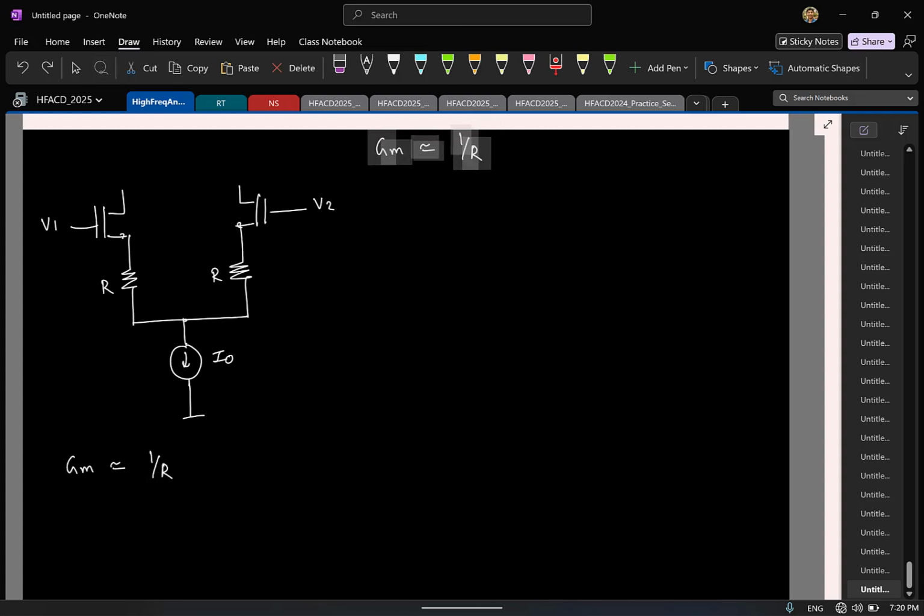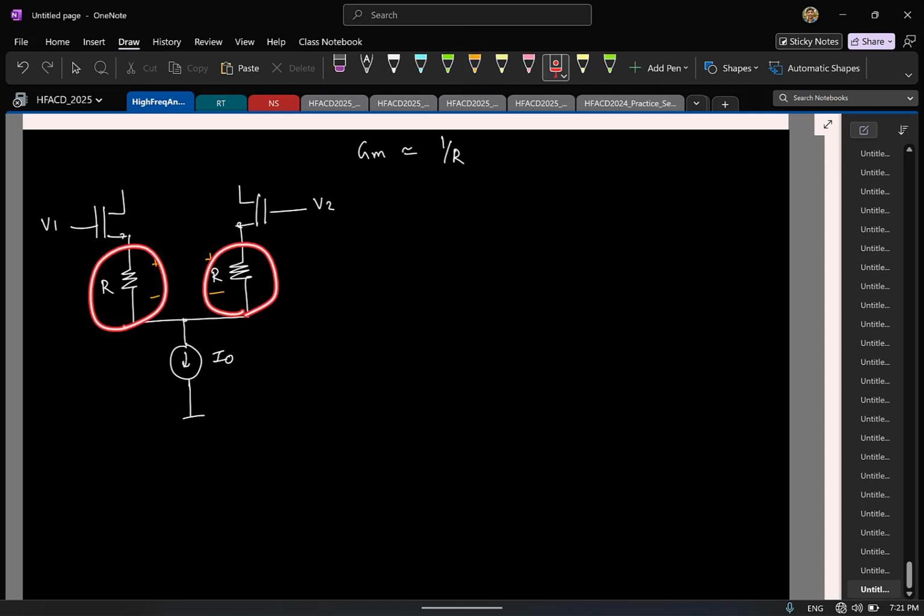Let me mark it here. Having problems is nice, because only then as engineers you all have jobs. The simplest problem is this: the moment you have a resistor here, the resistor is going to have a voltage drop across it, so it is going to eat up your swing limit. If your supply is very small, you might not be able to accommodate a voltage drop across the resistor. So let's see what you can do to overcome this.